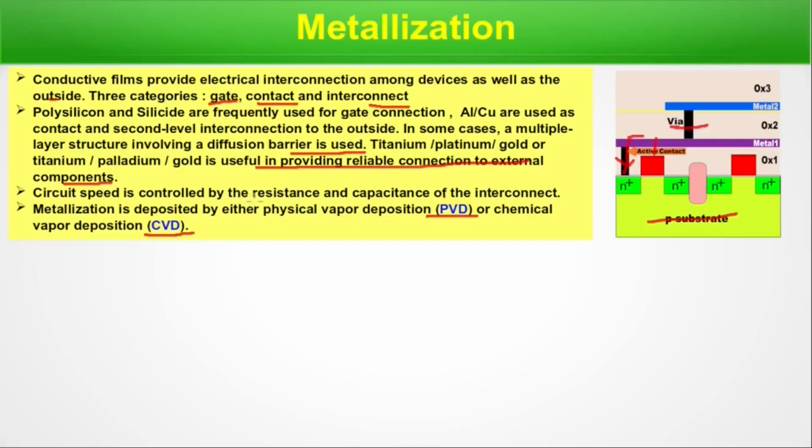Resistance and capacitance are not only parameters of the dimension but also intrinsic parameters of the material. So there are 2 factors which we can control. When we try to control circuit speed by controlling interconnect parameters, either we can change the material altogether, and the resistance and capacitance value will get changed. These are intrinsic to a material. Another point is we can change their dimensions. So cross section can be changed, length can be changed. So by that designing we can change the circuit speed.